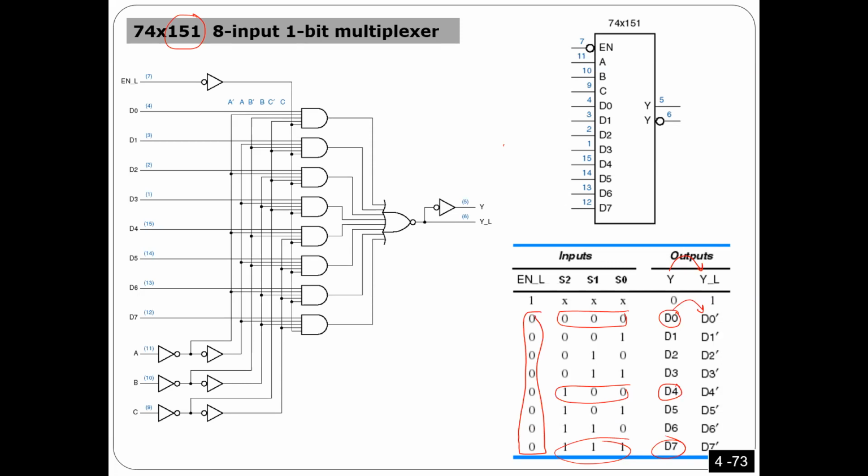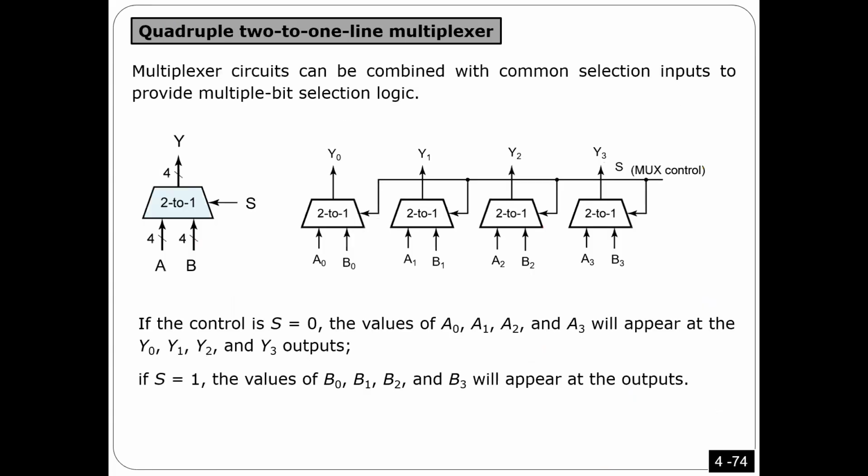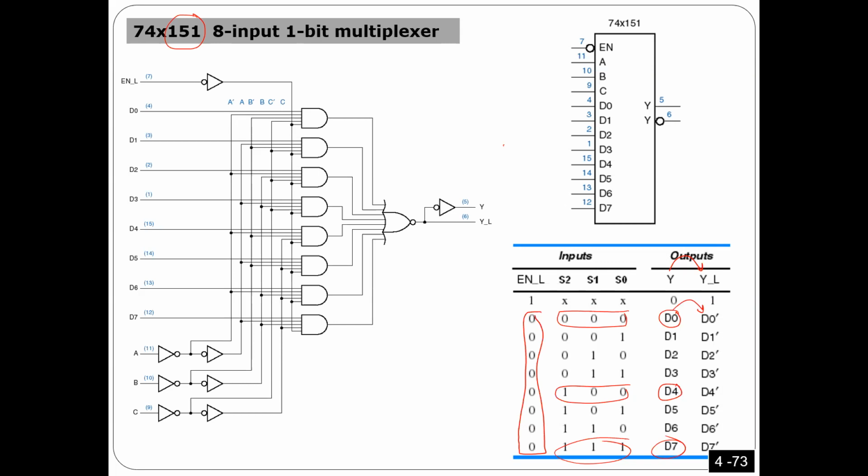Okay, again, guys, I explained: you should understand what an encoder is and how we designed it, very simple. Second, you should understand how I made a simple modification of the decoder to make a multiplexer, and the meaning of multiplexer, the concept and definition. A multiplexer has 2 to the power n inputs and selectors. It's like a switch: you select whether you want the output to get its input from here or here or here.